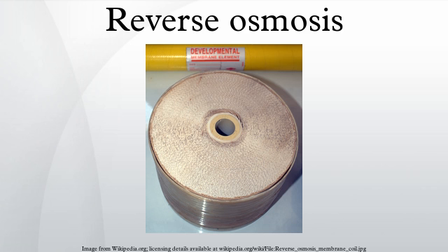In practice, a fraction of the living bacteria can and do pass through reverse osmosis membranes through minor imperfections, or bypass the membrane entirely through tiny leaks in surrounding seals. Thus, complete reverse osmosis systems may include additional water treatment stages that use ultraviolet light or ozone to prevent microbiological contamination. Membrane pore sizes can vary from 0.1 to 5,000 nm depending on filter type.